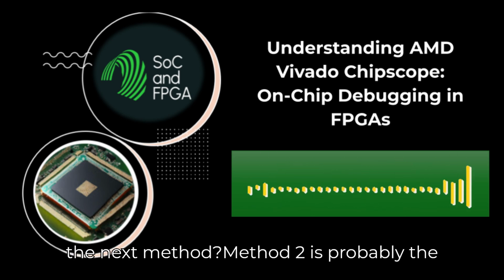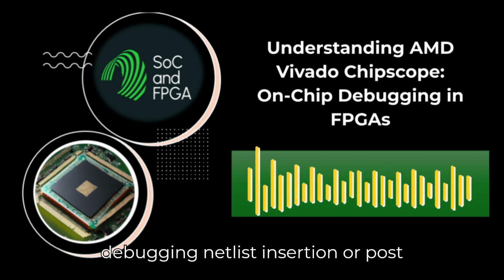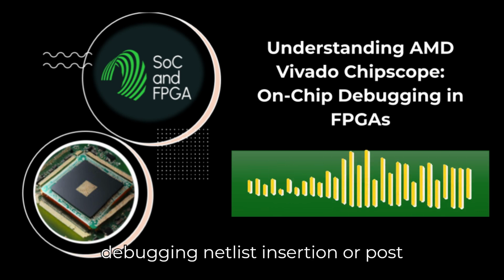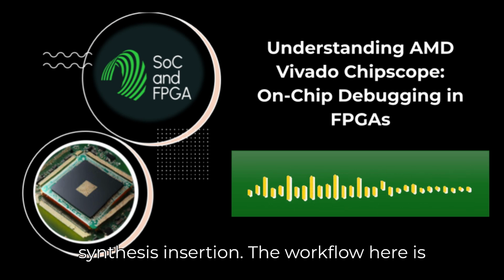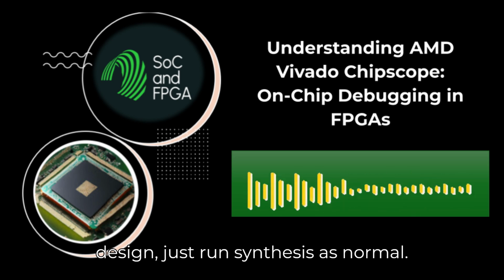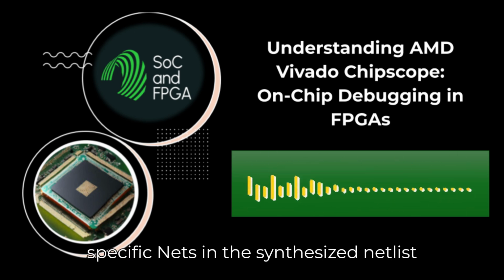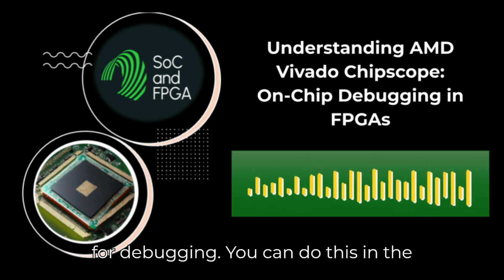Right. What's the next method? Method 2 is probably the most commonly used for general-purpose debugging. Netlist insertion, or post-synthesis insertion. Yeah. The workflow here is, first you synthesize your unmodified RTL design. Just run synthesis as normal. After synthesis, you then mark specific nets in the synthesized netlist for debugging.